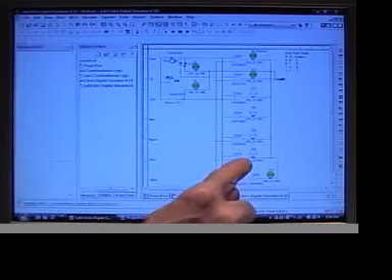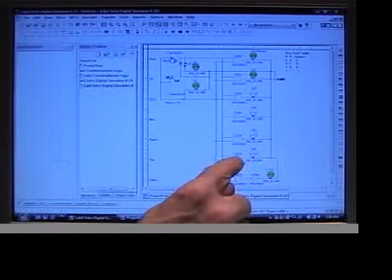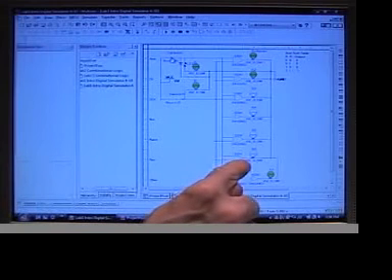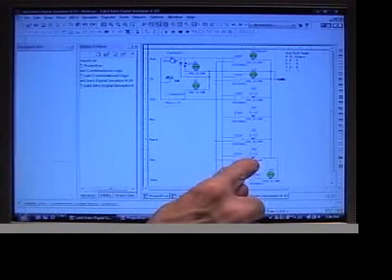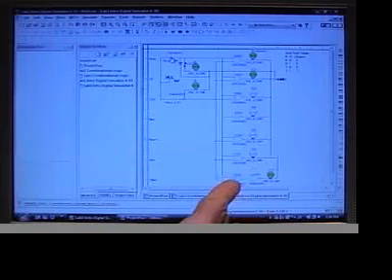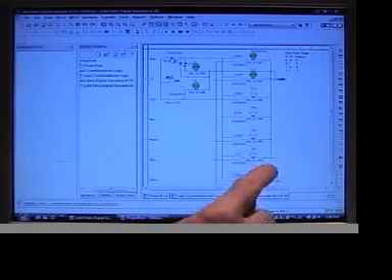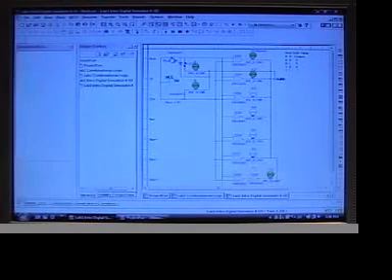The OR gate has two 1s on the input, so the OR gate has a 1 in the output, but the inverter makes it a 0 on the output. And the exclusive NOR gate, the combination of these two gates, now has a 1 in the output.